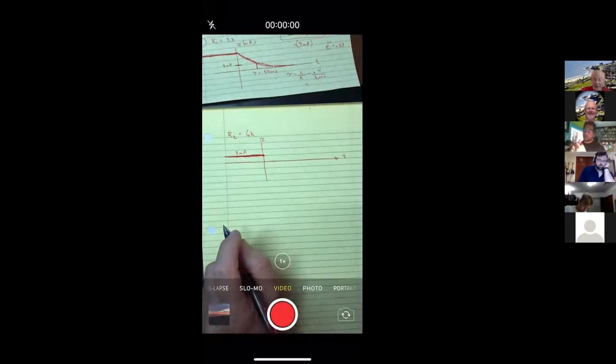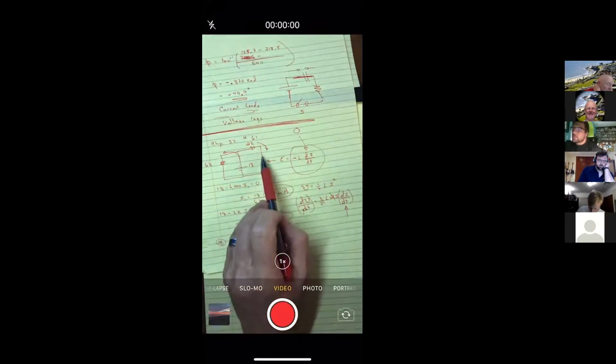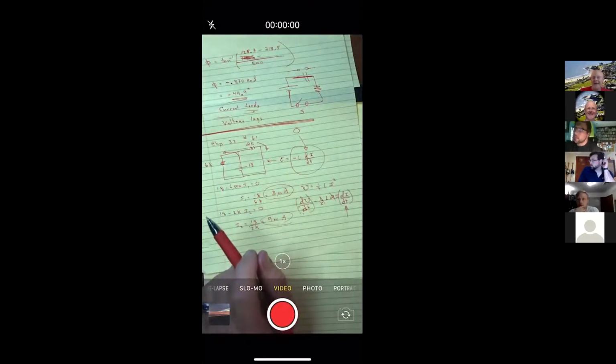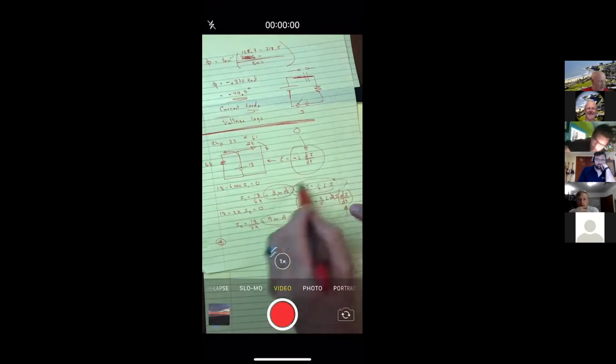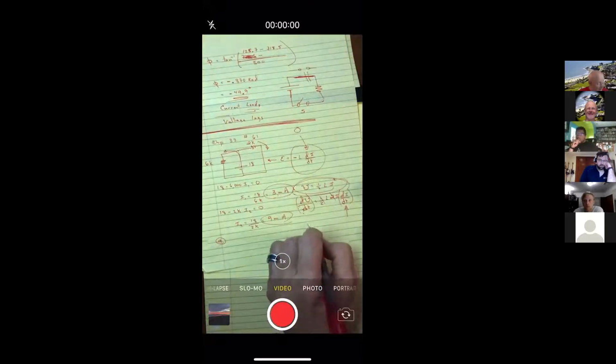And this is kind of interesting, because coming back to our circuit, remember I said that you couldn't change the current instantaneously, and I hope you caught this part, instantaneously in an inductor. That doesn't say anything about the resistor. So resistors didn't have this energy storage. So you can change them instantaneously. This argument does not apply for resistors. By the way, for capacitors, we did the same argument, that you couldn't change the voltage instantaneously.